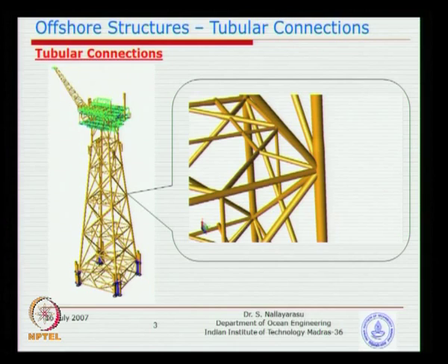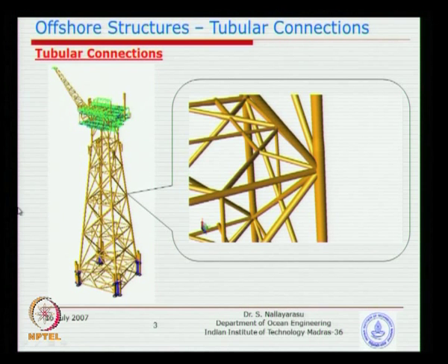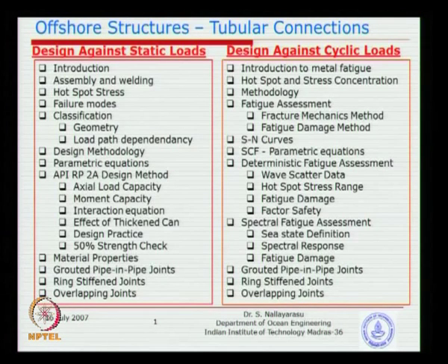So, you need to design the joint in such a way that it will never ever fail until all the members become plastic or near collapsing. You understand the idea. That means the factor of safety or the design constraints on the joint should be such that it should be the last one to fail. So, that is why we should give reasonable importance to the design criteria, understanding, and then application of parameters within the limits of what has been done